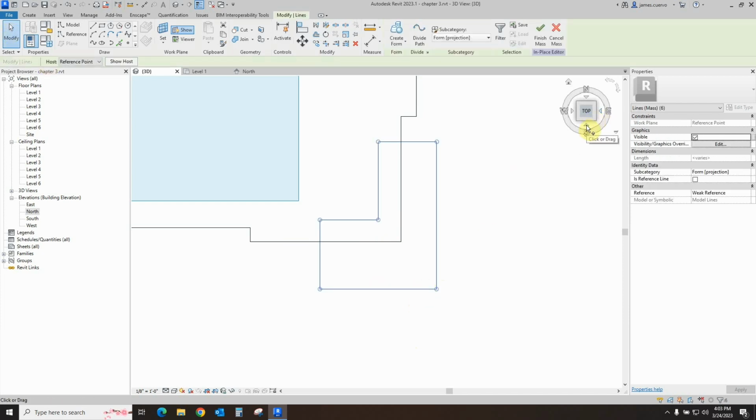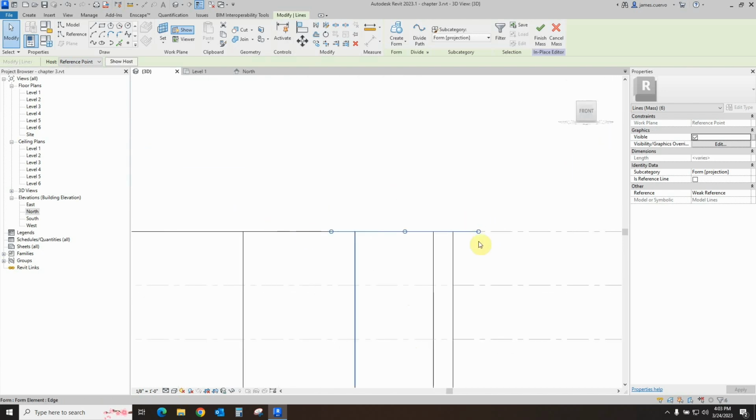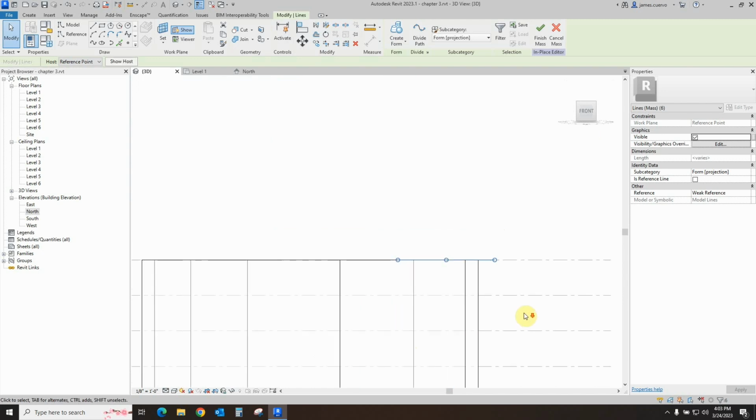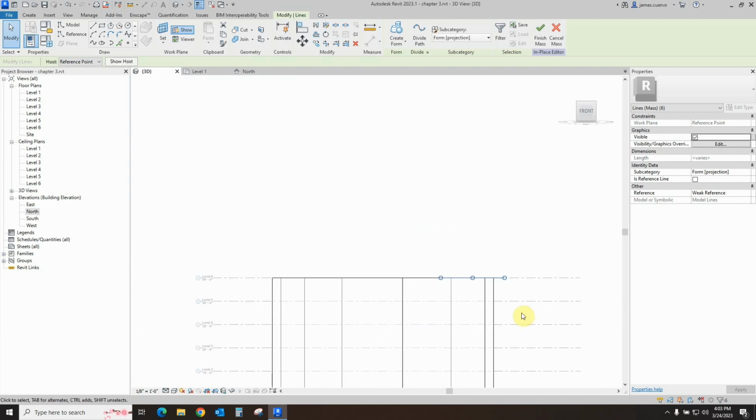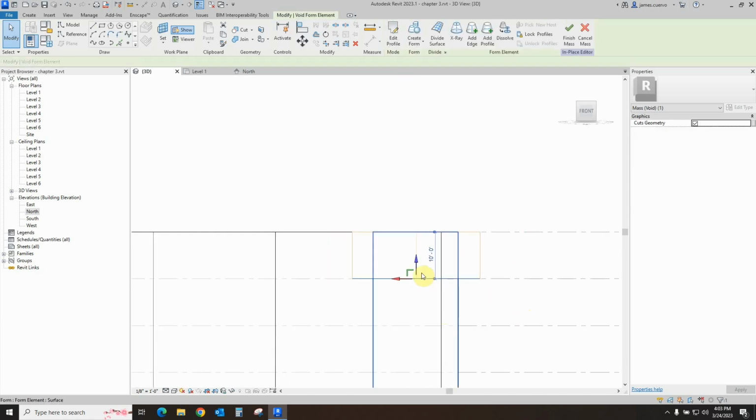Let's go into a south view, see where that shape is. Notice where it is. That's fine. We're going to place that balcony in level, what level is that? That's level 4 right here. And so let's go ahead and extrude by create form. This time we said it was going to be a void. We'll bring this bottom level down to level 4, which is right here.